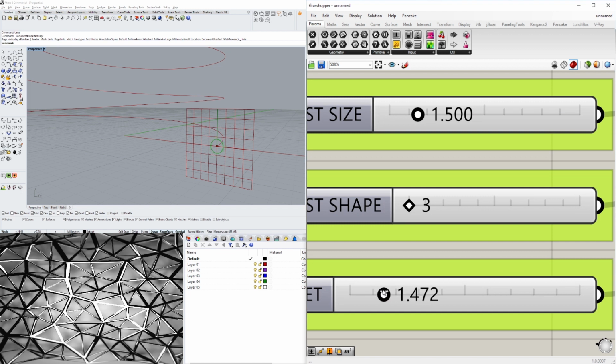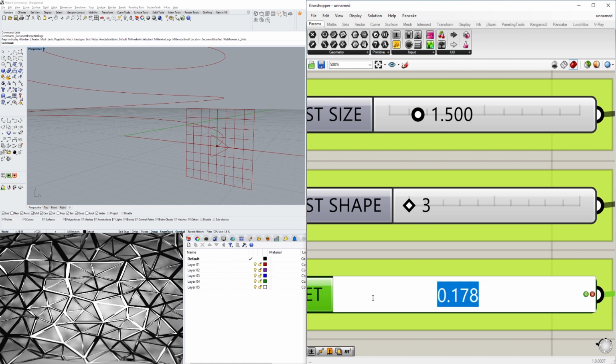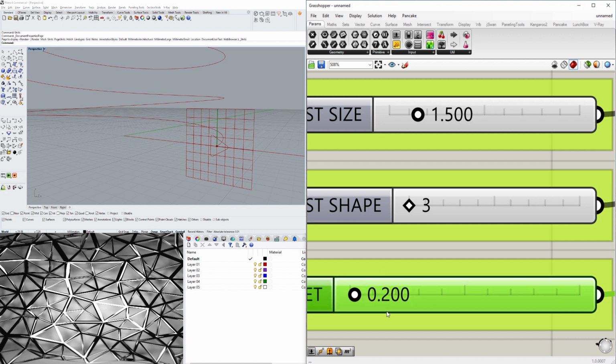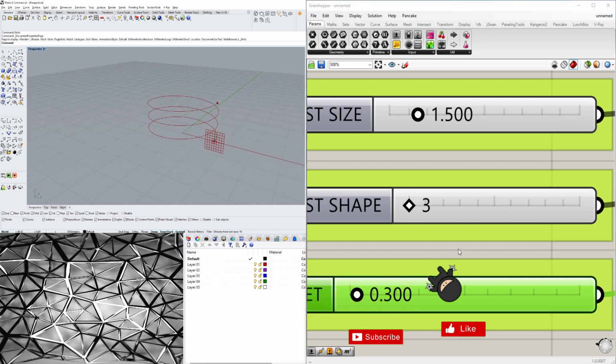And we can even create a circle, right? So the bigger the fillet that we create, we can end up with a circle. But I like to just have it a little bit rounded off. It helps when you create kind of straight edges like this for 3D printing. It gives us a little bit of issues. So I like to sometimes fillet it a little bit, even like 0.2 something or 0.3, which is not much really.